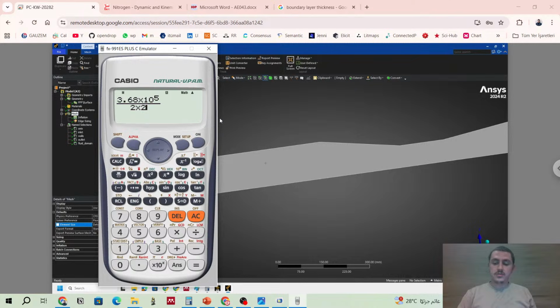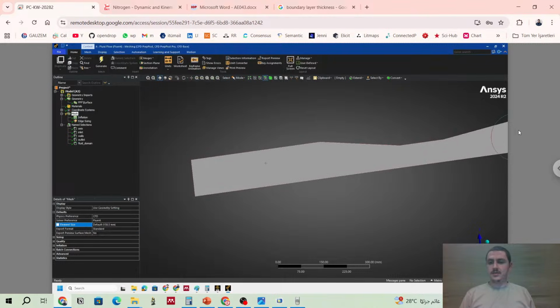So depending on my capability, I can increase it, and depending on the time that I want to spend on this, let's say 1.5. I think 2 is also good, because we are also using fine elements here. We are using a smaller size. Let's put 2 millimeters. Then see, maybe we need one more step. But let's generate. Then it will start consuming some time.